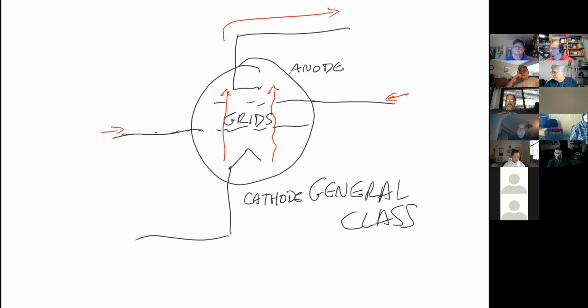Now, unlike a transistor, which will typically operate at, let's say, 12 to 24 volts, some as high as 48 volts, a vacuum tube, because you have to actually have a fairly high voltage, will operate at between, let's say, 250 up to 3,500 volts. So what does that mean about something that uses vacuum tubes? Dangerous. Yeah, you basically have to generate, let's say 3,500 volts, right? That's enough to really ruin your day if you stick your finger in and get a shock.